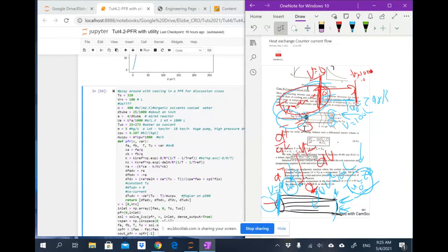Okay, so essentially we're going to check the plot of the coolant temperature. Yes, we are going to plot it, but we are also going to specifically ask for a value there at the outlet so that we can check, and by trial and error, we're going to change our inlet temperature of utility. So remember, it's not the inlet temperature. When I speak about inlet temperature, I am not deliberately confusing you. It is the temperature of the utility at the point where volume is 0 from the perspective of my integration boundaries. Right. Okay, so let's do it.